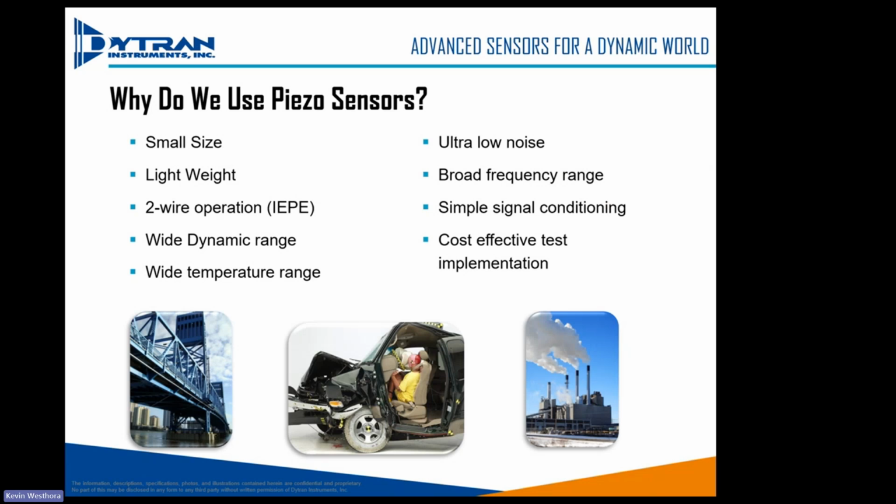We offer wide temperature ranges. The SpaceX launch last night had sensors on it that are rated to minus 320 F, and we also make sensors that are rated to plus 1200 F. So this same technology can go minus 300 to plus 1200. It's quite amazing. We do offer at Dytran a lot of DC MEMS variable capacitance sensors, and they are the lowest noise sensors on the market. But if you compared a DC MEMS sensor to a piezoelectric sensor, you would see an exponential level difference of noise on a piezoelectric sensor. Piezoelectric sensors have amazing low noise floors.